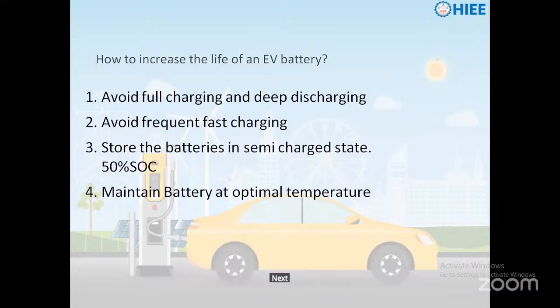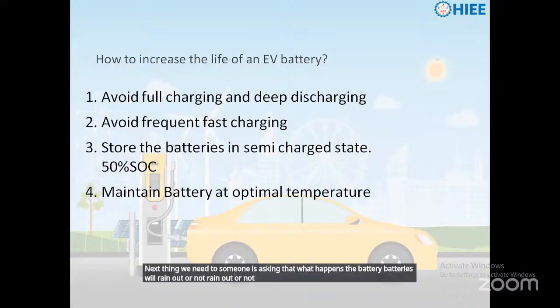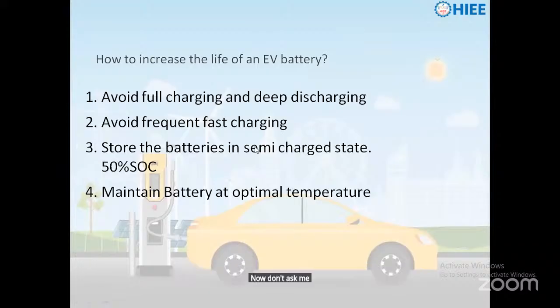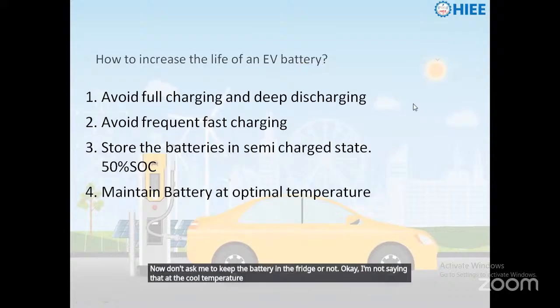Next thing is storage. Someone is asking whether the batteries will drain out or not. Batteries will drain out by default, but whenever you need to store the batteries, always try to store them in a semi-charged state with 50% state of charge, and always try to maintain the battery at the optimal temperature. So now don't ask me to keep the battery in the fridge or not. I'm not saying keep it at a cool temperature. I'm trying to say maintain it at the optimal temperature. Okay, chalo. So these are the major tips given by me to increase your battery life.